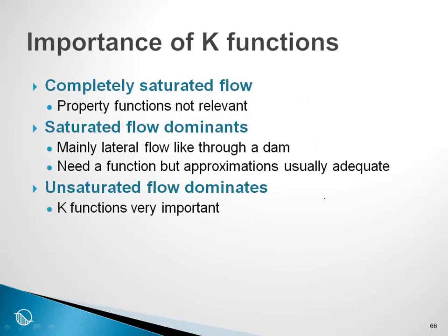Returning then to the question, the importance of the conductivity function. Completely saturated, the function is not important at all, and the property functions are not relative. Saturated flow, where saturated flow dominates, mainly lateral flow like through a dam, we need a function but an approximation of the function is more than adequate. When we have purely unsaturated flow and unsaturated flow dominates, then the conductivity function is very important.